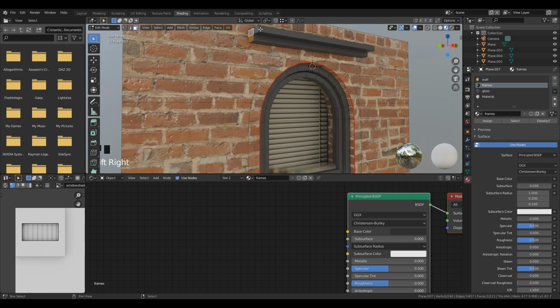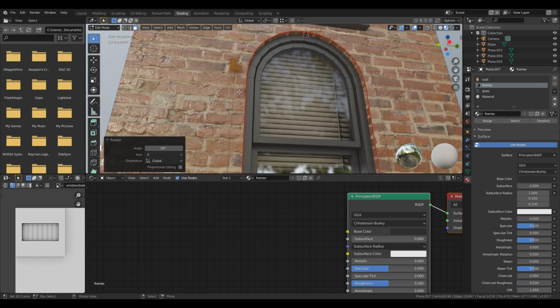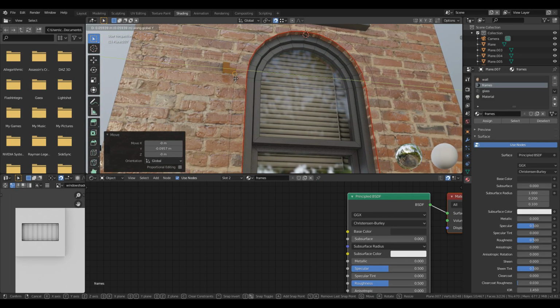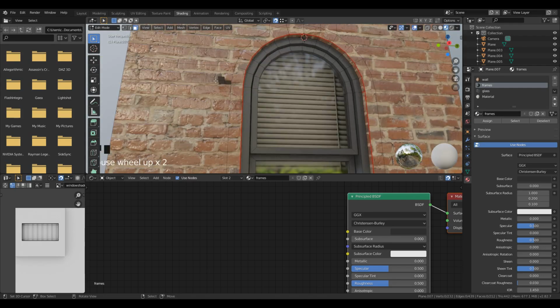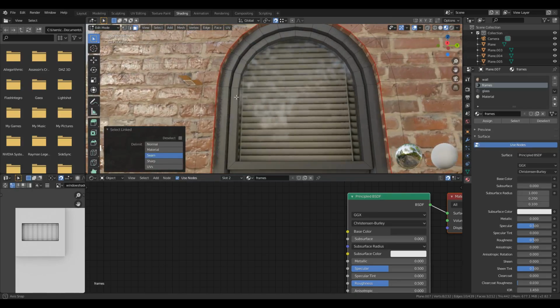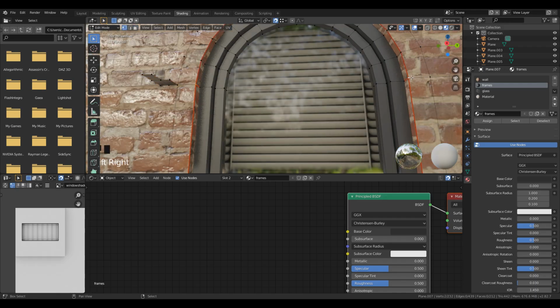Now just select the side faces of the upper window design and duplicate them. And snap them on the z-axis where the window faces are starting to spin. Then just delete the upper design and use the same spin tool for it as we did before for the wall. Just remember the position of the 3D cursor is very important for the spin tool, otherwise you will not get what you want.